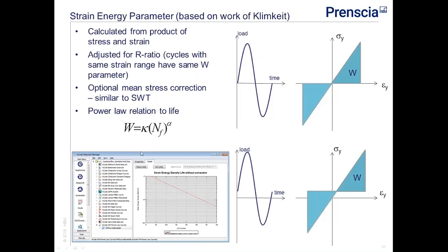And it's a method that seems to work quite well, basically because the directions in which a material has lower fatigue strength are also the directions where it's less stiff. So one of the big advantages of this method, as I mentioned before, is that if it works, we should only have to test one series of specimens to characterize a material rather than 3 different orientations.